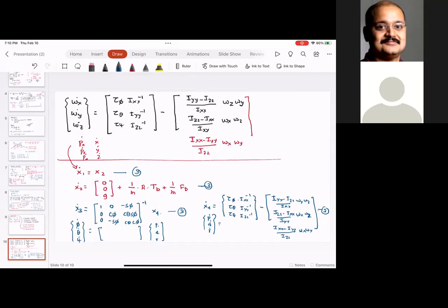I'm going to stop here today, but I just want to tell you that this lesson, in my personal opinion, is the most important lesson in robotics too, because this is where you understand the simulation. Once you have the differential equation of motion, the next part is just tuning or changing the values of tau based on some type of control algorithm, and then making sure that the quadcopter is in stable hover, or is able to follow a particular path, and so on.